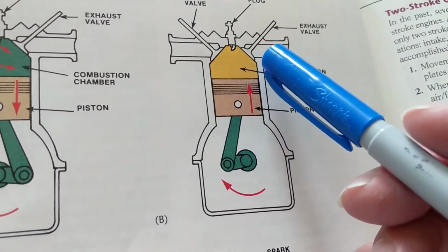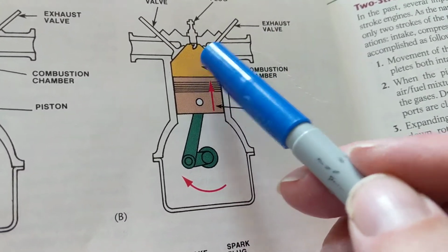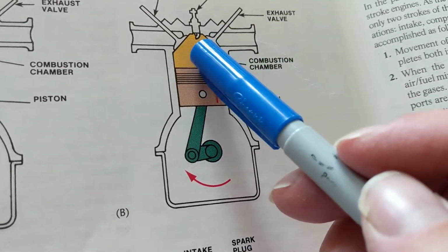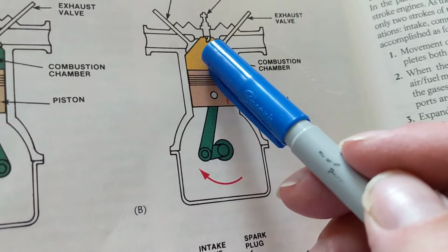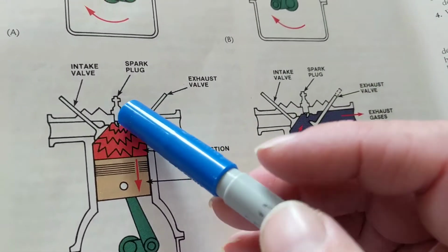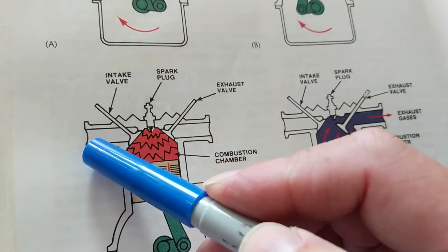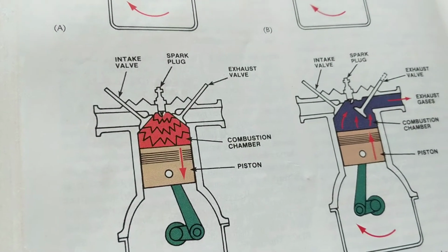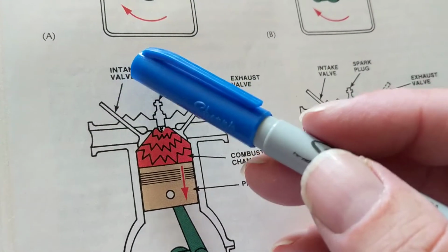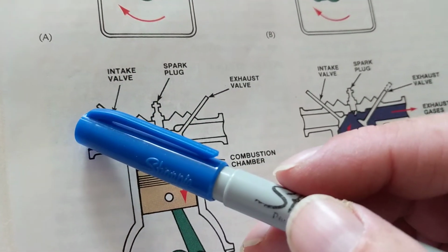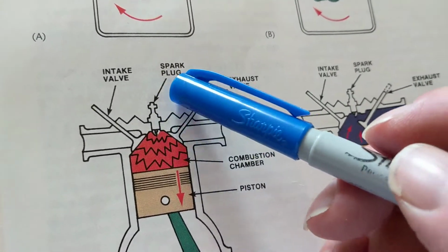We want that. Again, now it's closed. Now we're compressing it. Oh, that's great. The pressure, temperature, everything goes up. The piston head compresses it, squeezes it. When that happens, boom, spark comes in. Who controls the spark? We said fuel injectors are controlled by the computer. You control air. The computer controls the fuel injector. Who controls the spark? You? No. The computer again. PCM.